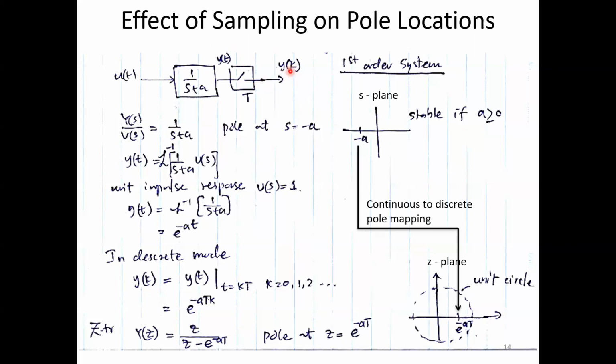But it is obvious, right? Your y[k] should represent y(t) accurately. So if you look at the transfer function, Y(s) over U(s), the continuous time plant, it is 1 over s plus a if it is a first order plant. We are taking a first order plant for simplicity.